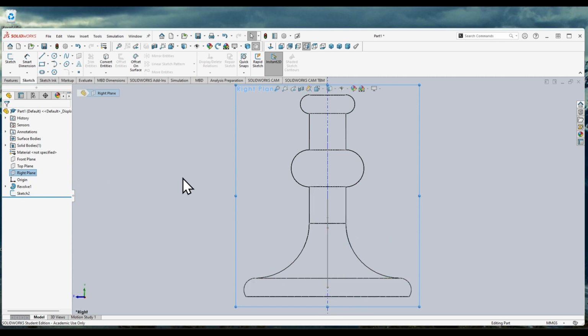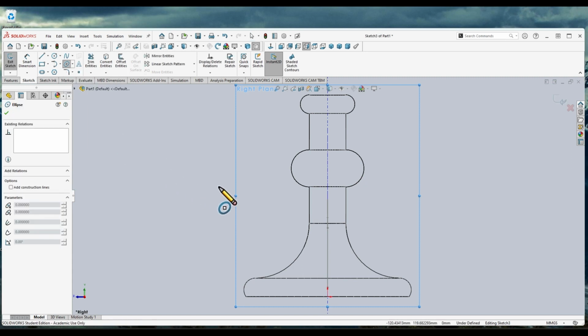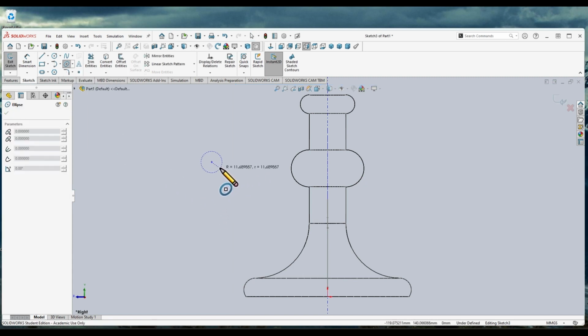And the instructions in SolidWorks say we're going to draw an ellipse next. We haven't used this ellipse tool either. When you hit the little arrow next to it, there are some options, but we want the ellipse itself. So I click on that one, and I can literally draw this anywhere. So I'm going to draw it over here.